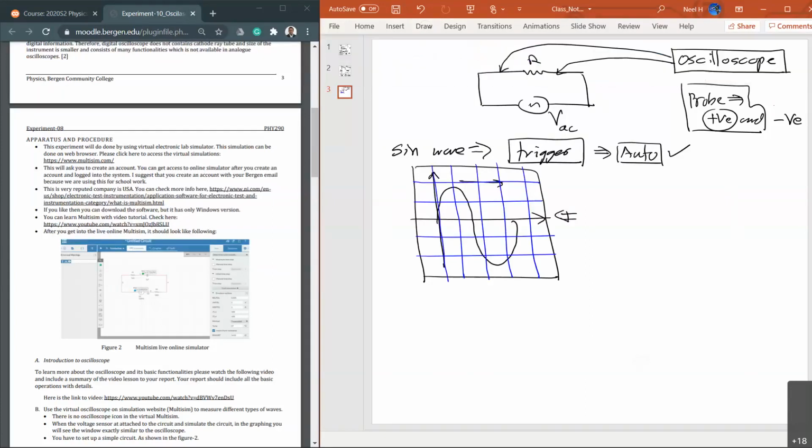Let's say I have channel 1 and channel 2. Channel 1 has a control, right? Channel 1 has a voltage control. Usually if it is an analog type oscilloscope, it's a knob. You rotate the knob and around the knob it shows certain values. What it says, technically, is voltage per division. Technically this division means one of these lines right here, right?